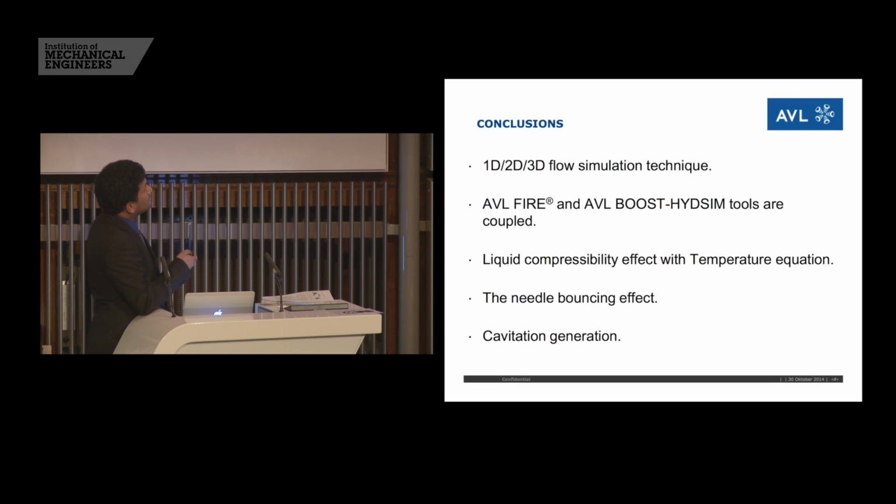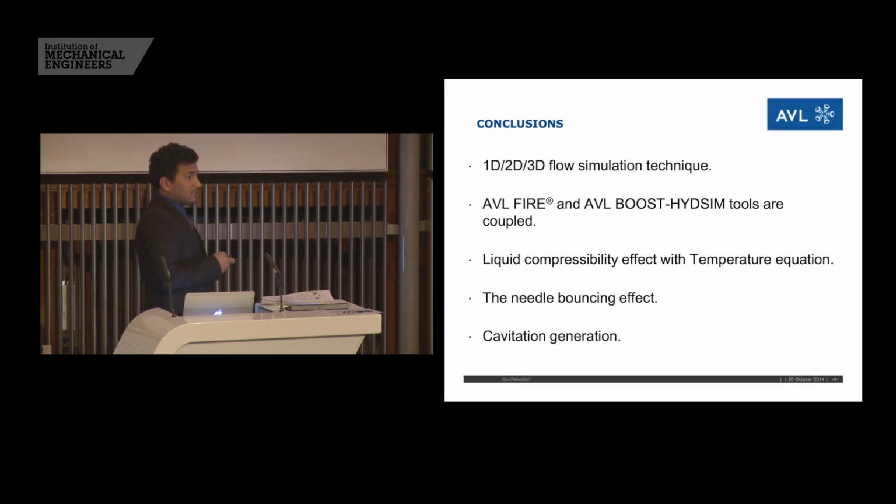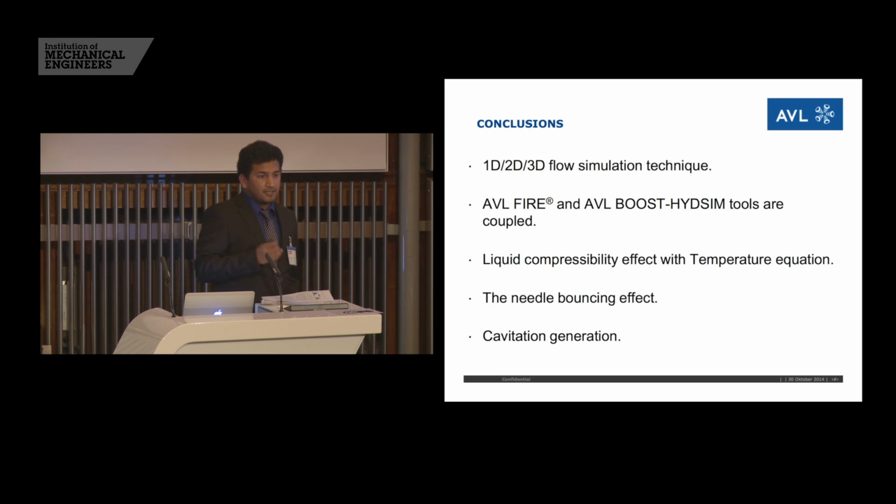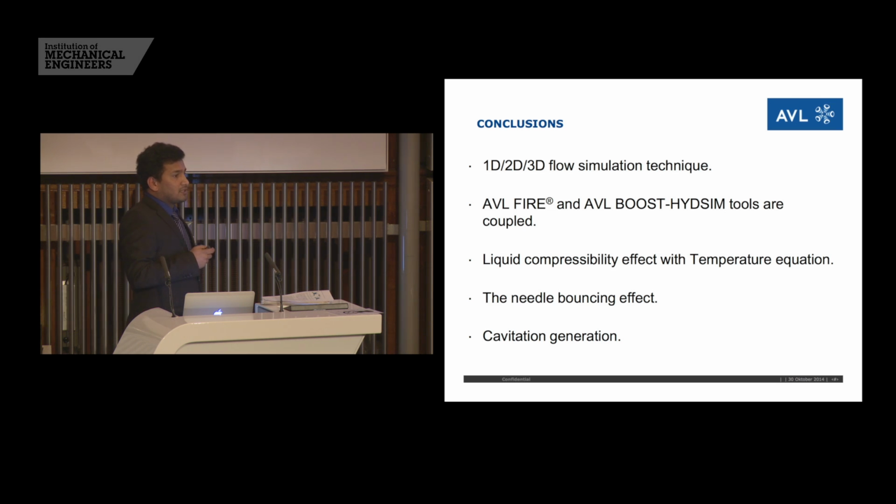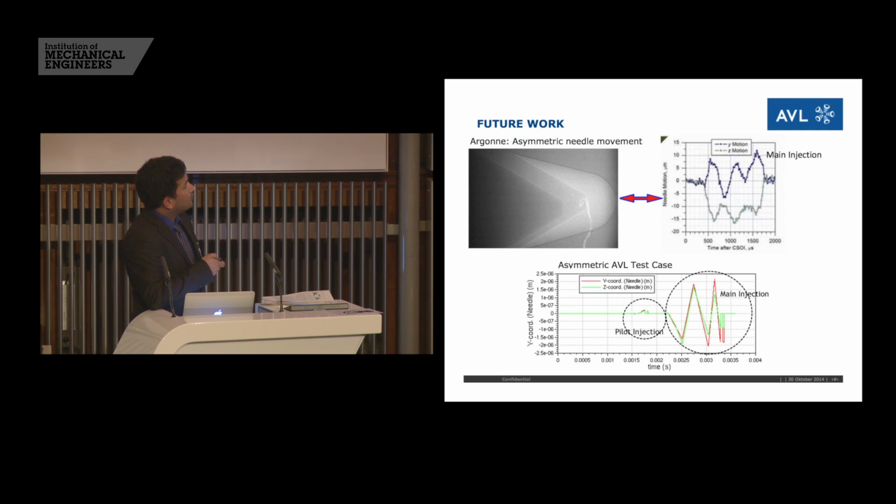So in the conclusions, in this present case, we coupled a 1D, 2D, 3D simulation with the AVL FIRE and HEATSIM tools. Additionally, we included the temperature enthalpy equation with liquid compressibility effects, where we saw the liquid compressibility effects really damp the forces. And the needle bouncing effect is really important for the cavitation generation, which is really asymmetric for the asymmetric mesh case. And for the future work, we are working on it now.